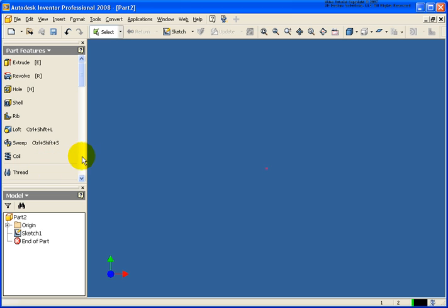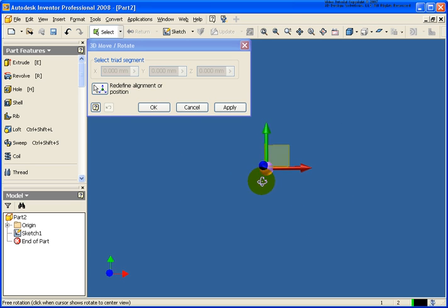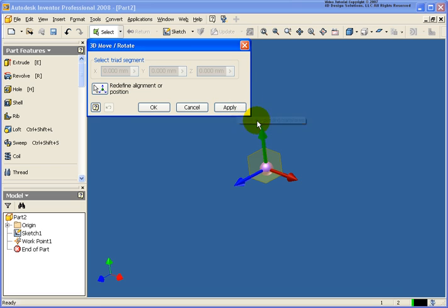What a grounded work point is going to allow me to do is place it depending upon selected geometry. So the first one I'm going to place is going to be at my 0, 0 point. I'm going to spin that around so we can see it a little bit cleaner, and I'm going to click apply to place one. Now I can place this next work point based on specific geometry. If I want it to go so far in the X direction, I can just click on the X arrow and type in a value. So let's go out 20 millimeters and apply.